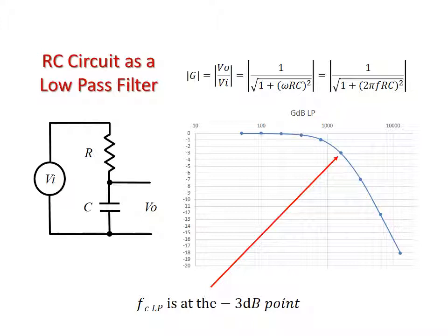So here we're going to look at our frequencies versus our attenuation, so how much quieter the signal gets. On the y-axis we're looking at decibels for the unit, and on the x-axis we're looking at frequency. From the previous chart, we found the frequency at around 1,100. So in this chart, we can look at the attenuation at that frequency. If we drag over exactly from that point, 1,100 as the frequency, to the y-axis, we can see that's at about -3 decibels.